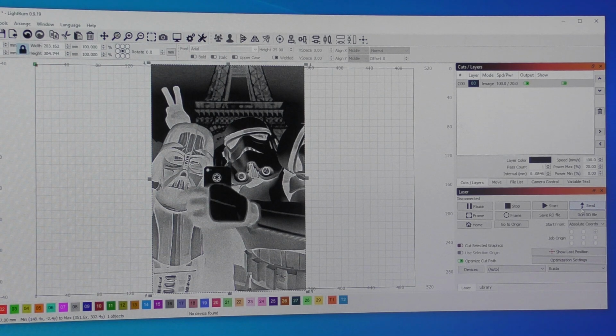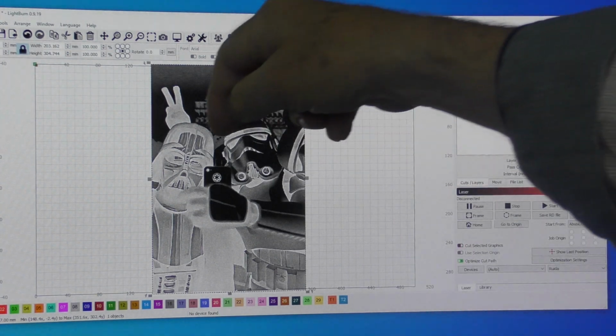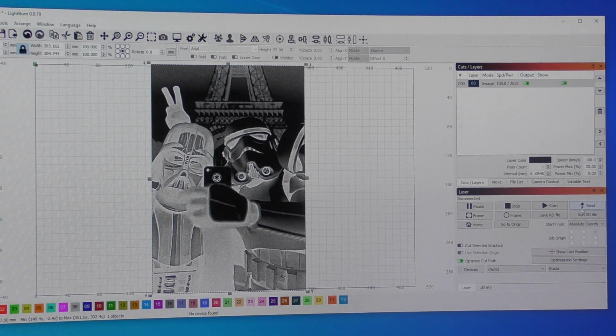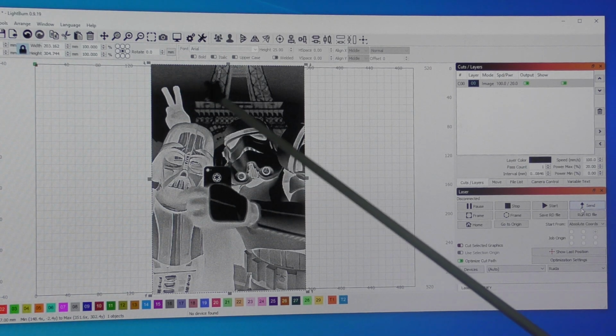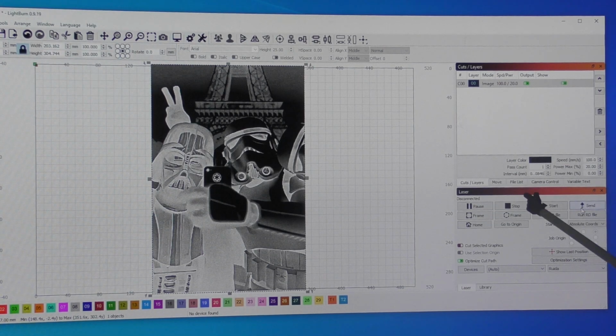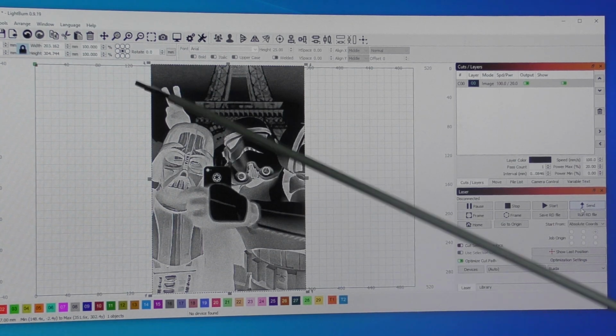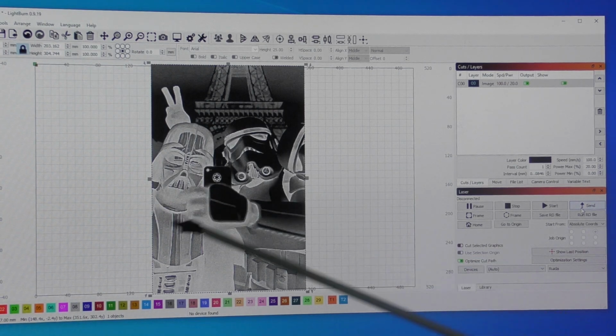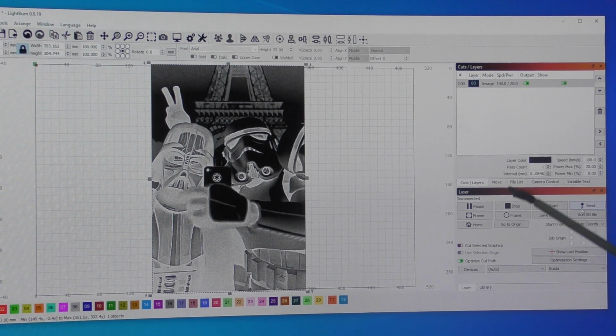What I'm really now doing is I'm creating an aliasing pattern. Lightburn is going to turn the tube on and off for every single pixel that it sees. So there's going to be no problem in the x-axis, but the problem is going to be in the y-axis because he's stepping at a rate which doesn't match the pixel size. So you're naturally going to generate bands in the y-axis because of this difference in the pixel size and the y-axis step. Haha! So that's the reason why Matthew is getting banding. No, it isn't.